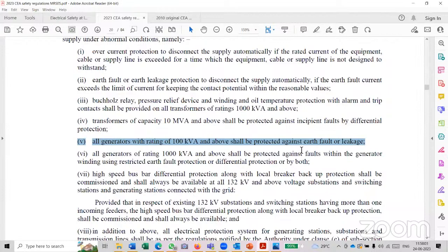So the thing is, we should not read the title as voltage exceeding 650. This occurs in several places because of this classification. Interlock, earthing, most of the things are common to all voltages. But by defining this 650, there should be some special category. If it exceeds 11 kV or 33 kV, it is an EHV installation, and there requires some stringent measures. It cannot be for all protection measures like parallel operation or interlock. That's what I feel. Finally, the implementer should avoid the words at voltage exceeding 650. Remove it.